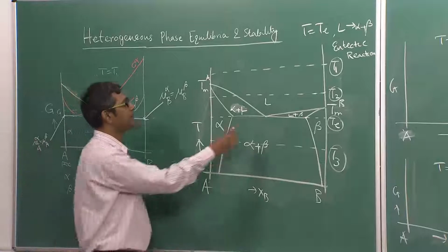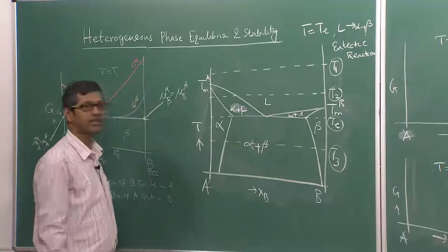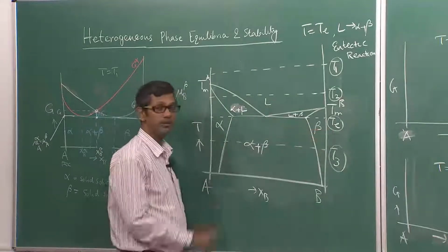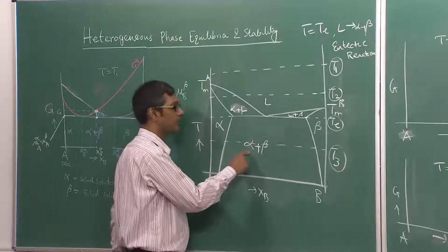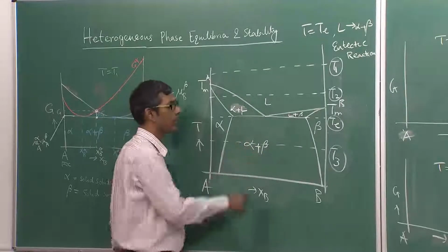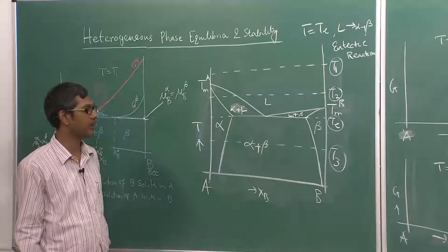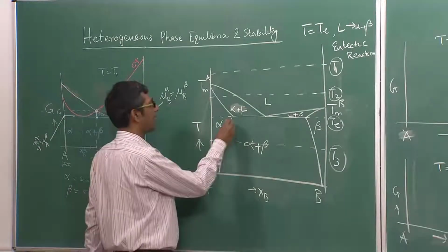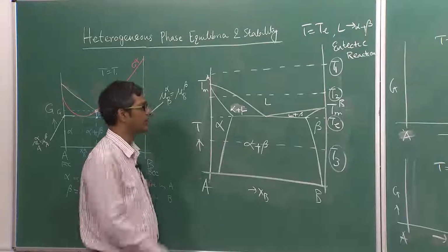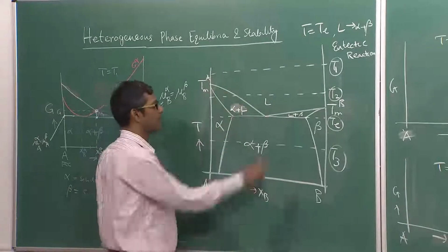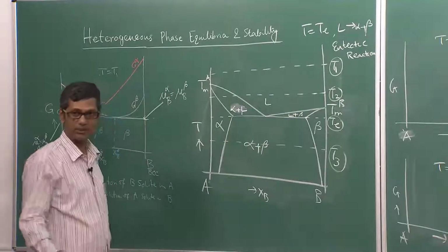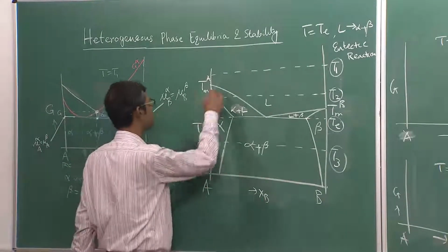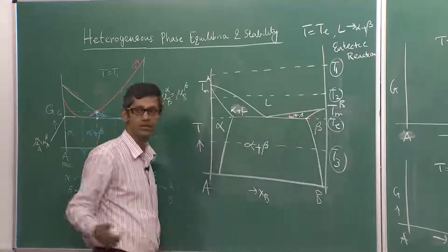And in between you have a eutectic reaction. This reaction tells you that liquid is stable until the temperature TE, but below the temperature TE, liquid undergoes transformation leading to formation of alpha and beta together simultaneously. And that is basically the eutectic reaction. Therefore, I have two sets of regimes, liquid plus alpha and liquid plus beta. We can think of this curve as nothing but a superimposition of two isomorphous systems. This is one, that is another one, which I will show you at the end.